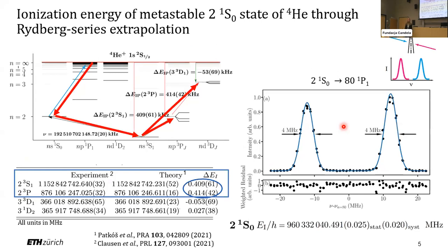The question was if we intentionally misaligned the laser beam. Yes, so we have the laser beam at near right angles, but we intentionally introduce an angle such that with the retroreflection we get the Doppler shift in the opposite direction, so we can resolve two Doppler components.